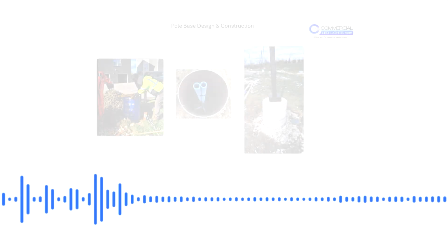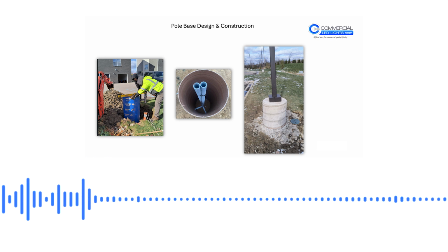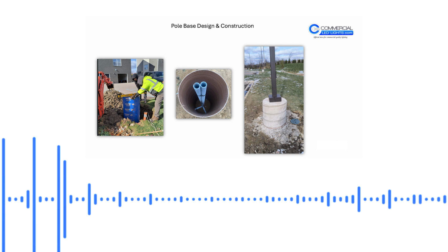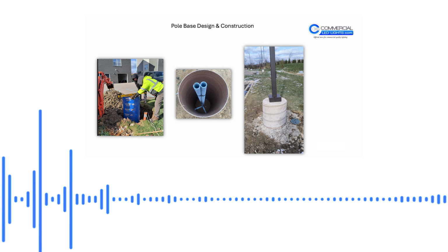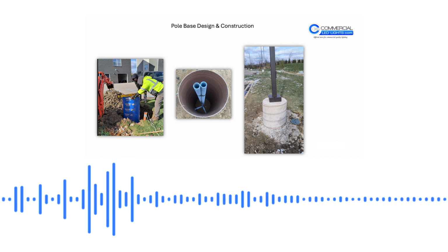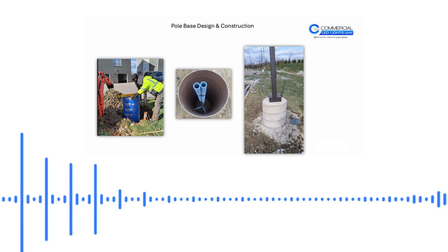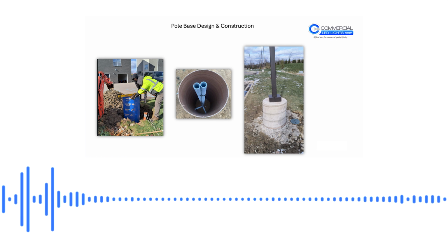So really the last thing is you've got to anchor this pole in some manner. And then we would verify the foundation and the anchor points, and send those to typically the contractor, and they go about pouring the footing and putting in the anchor bolts that we provide, along with the template, so they can get all that buttoned up.